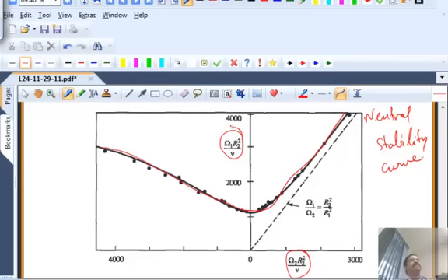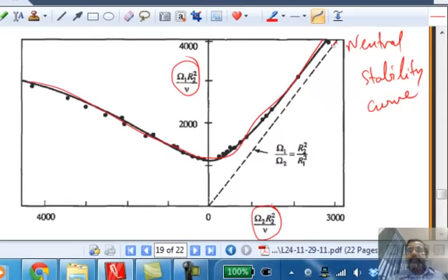And earlier, Rayleigh did an analysis of the inviscid flow. What is inviscid flow? Do you remember? Irrotational. When you throw the viscous term away completely. Okay. So he found the stability boundary to be this. That is solving the Euler equation, a similar problem for the Euler equation. But Taylor did it for the full Navier-Stokes equation and obtained the data points from his experiments.